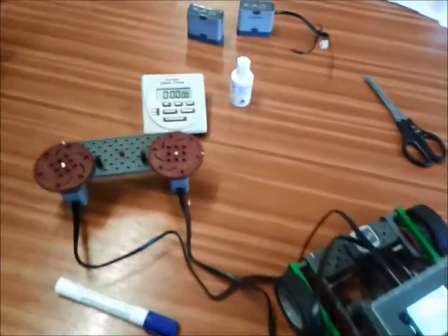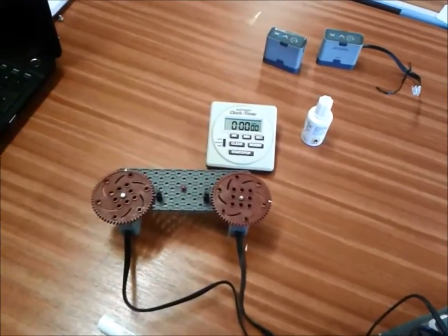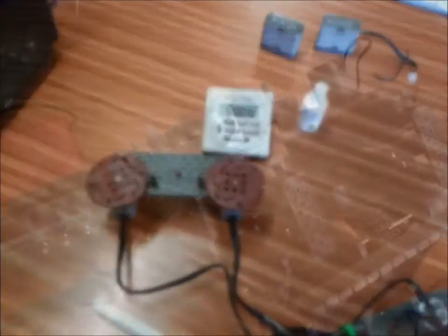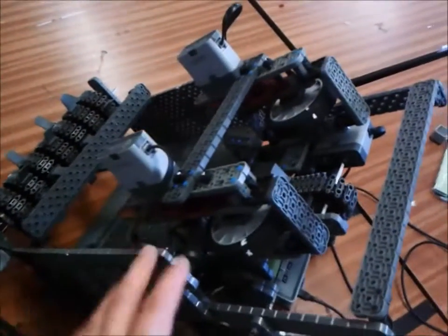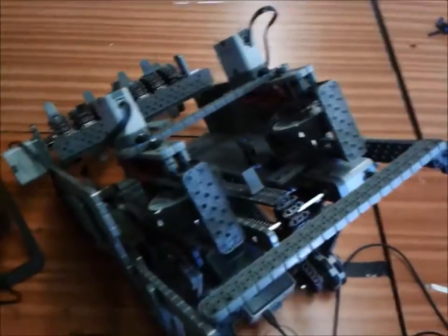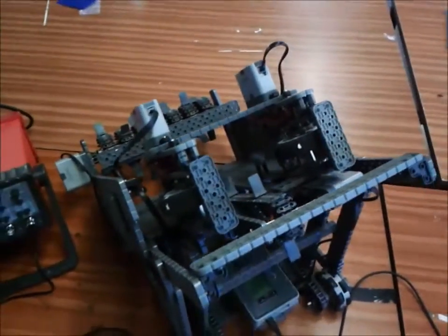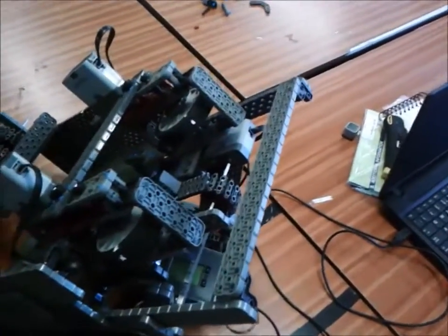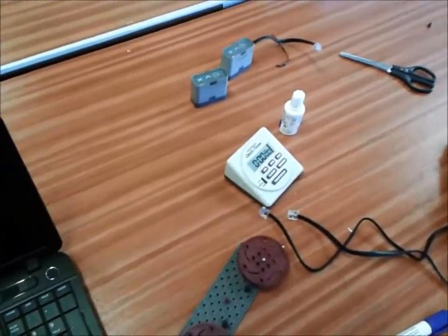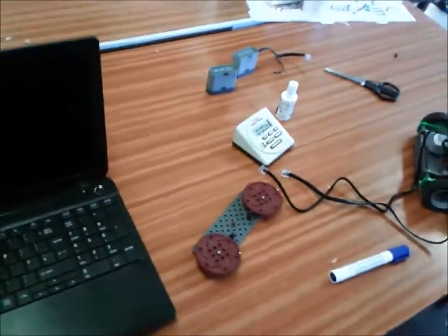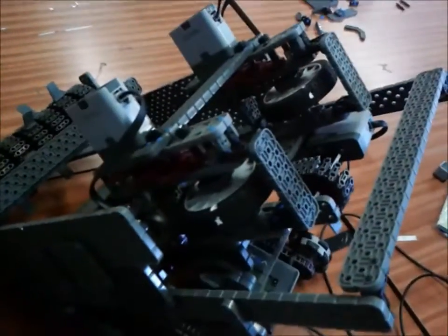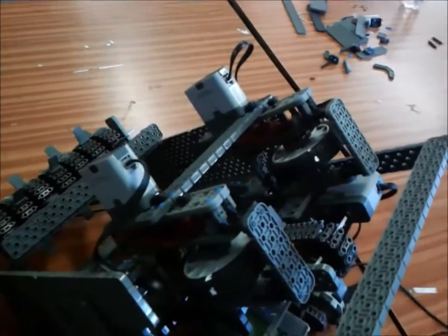So what I'm going to do now is put these motors back onto my robot on the 9:1 setting on the gearbox. So I'm just going to pop those back on. So the motors are back on the robot, and now what I'm going to do is try and measure the flywheel speed. Now the flywheels are going 9 times faster than what the motor turns, and when the motor was spinning on our test rig, it was relatively easy to count 2 rotations a second. On our flywheels, we're going to go 9 times faster than that, and to count it with the eye is probably not going to be possible.